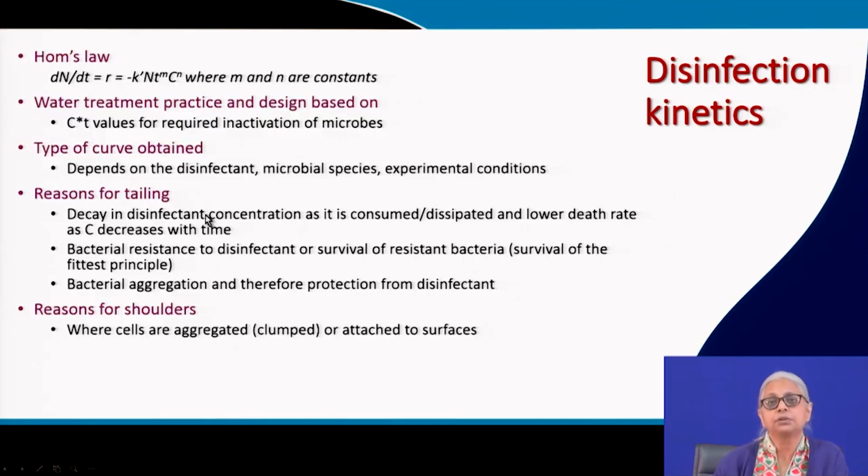The disinfectant concentration is being dissipated, it's being consumed, in the process of inactivating the microbes. Now, in this particular Chick-Watson law, we are assuming that the disinfectant concentration is remaining constant, which is not true. We know for a fact that it gets consumed or dissipated.